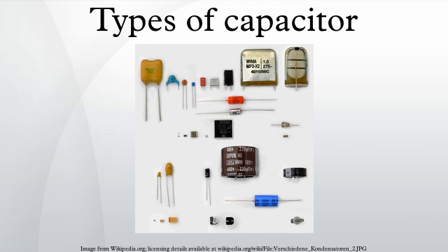Supercapacitors support a broad spectrum of applications for power and energy requirements, including low supply current during longer times for memory backup in electronic equipment, power electronics that require very short, high current, as in the KERS system in Formula One cars, and recovery of braking energy for vehicles such as buses and trains. Supercapacitors are rarely interchangeable, especially those with higher energy densities.